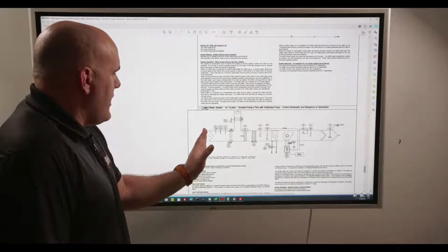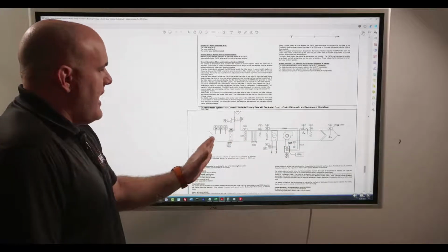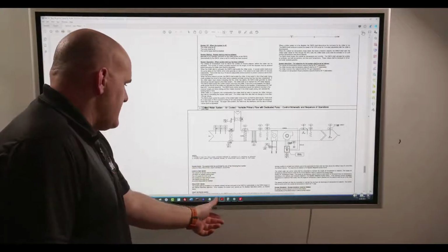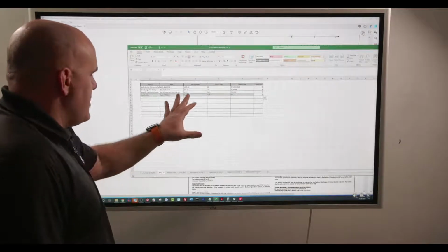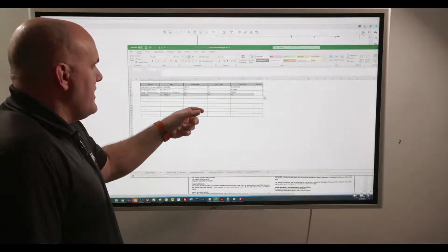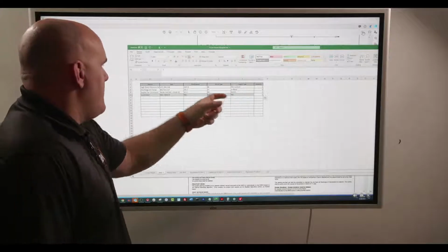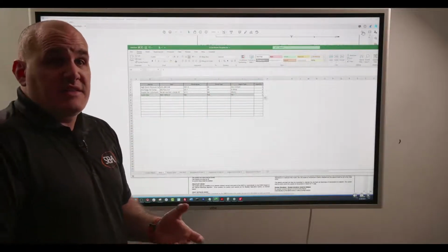So I would start in the back and go through all my inputs and figure out those, and then I would go through all my outputs and figure out those. And those are going to go on a dedicated page for the air handler unit. So I would list out my point names, my point types, the signal type, and the part numbers. I would validate this against the specification.